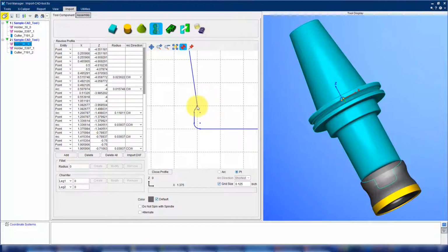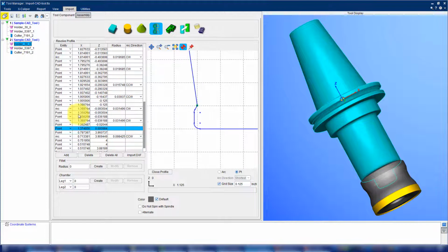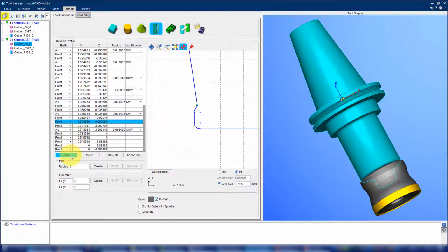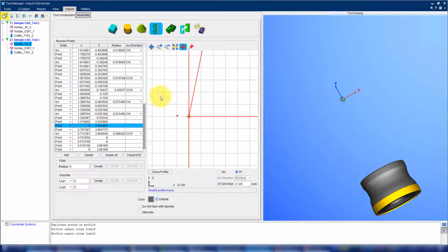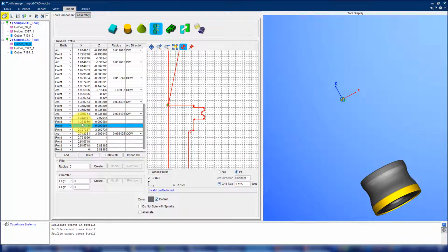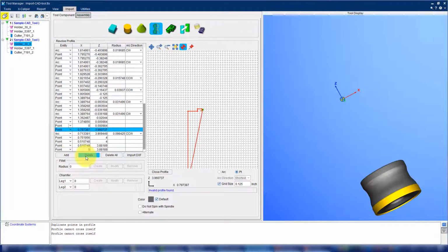For example, we can remove the taper portion of the holder as it is not necessary for the simulation accuracy. This method can also be used to easily modify standard holders which have been modified for production reasons, such as extra clearance or other modifications.